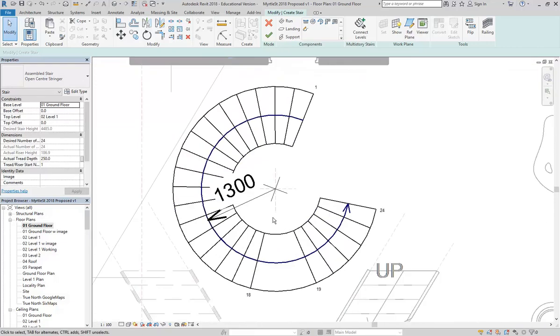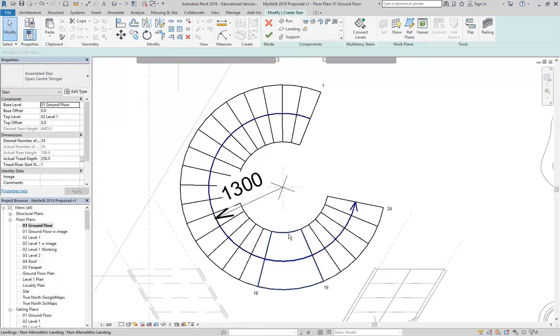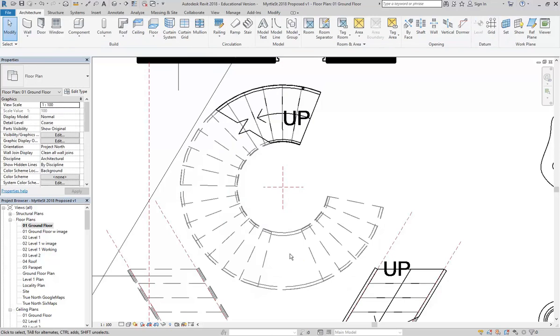So here though you can see obviously the shape, and so we'd have the curve coming up here, and that'd be one beam that'd curve up nicely, but then it has to go straight here. So that's a cranked beam, which is a difficult thing structurally. A cranked beam is just one that changes angle. They basically do the joint with a weld, and it makes a firm joint. So you can do that, but it's still not the best structure. And if I finish this and have a look at it in 3D, you're going to see straight away why it's a problem.